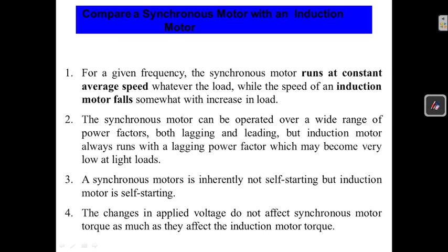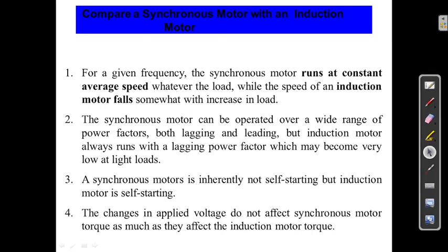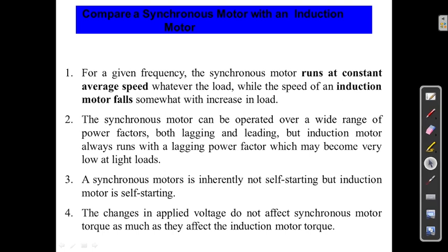Good day to all. Now we are going to see the comparison of the synchronous motor with the induction motor. For a given frequency, the synchronous motor runs at a constant average speed, whatever the load is, while the speed of the induction motor falls somewhat with increase in the load. The synchronous motor can be operated over a wide range of power factors, both lagging and leading.